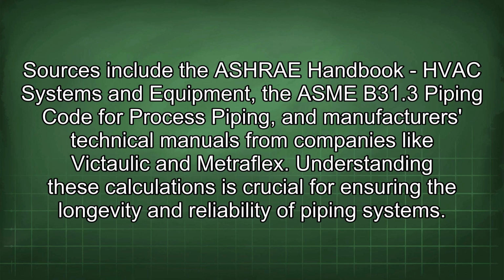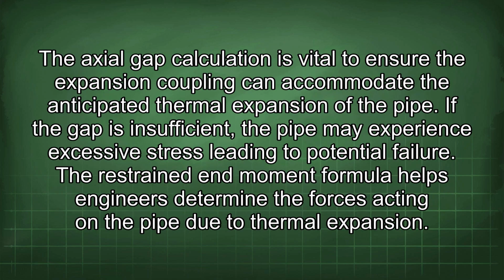Understanding these calculations is crucial for ensuring the longevity and reliability of piping systems. The axial gap calculation is vital to ensure the expansion coupling can accommodate the anticipated thermal expansion of the pipe. If the gap is insufficient, the pipe may experience excessive stress leading to potential failure.